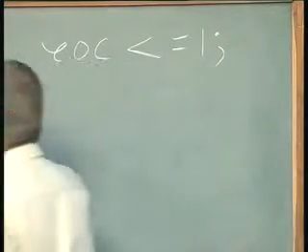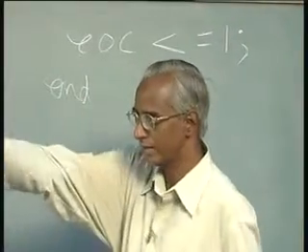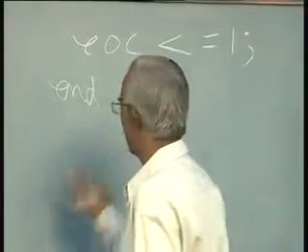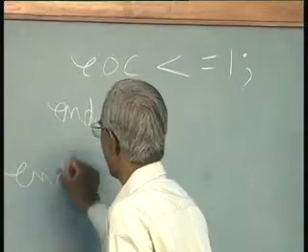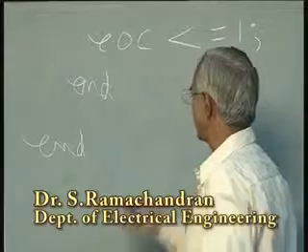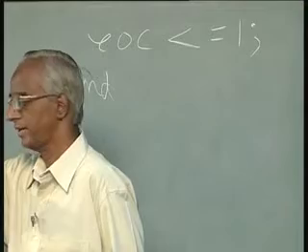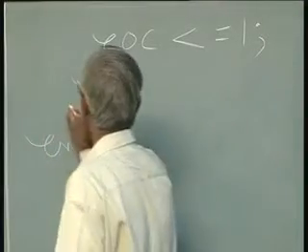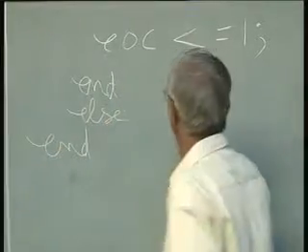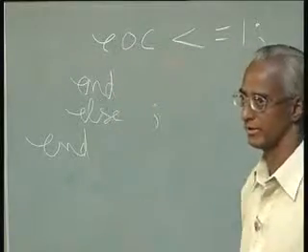And then what follows is one end. This corresponds to the end of the begin on the second line as such. And then you have one more end because we started with one more begin right at the top after the always statement. So corresponding to this end, we also have to add one else because we have not accounted for that. So that else is put here. And since we are not interested in outputting anything, you just put a semicolon, implying that it's a null statement as such. So this we'll have to incorporate.